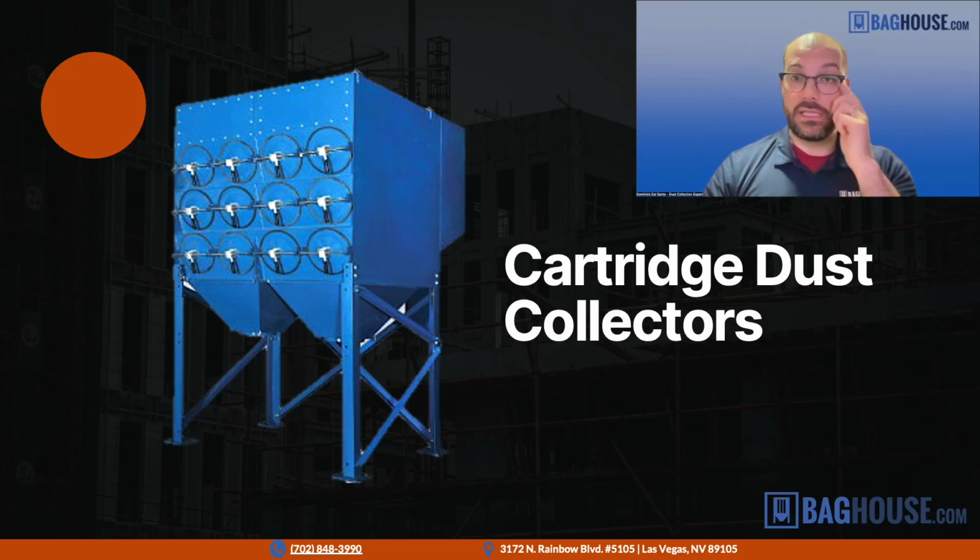So usually we see these retrofitted into existing baghouses, but sometimes we do new systems with them as well for mining and cement. More often they're used when we have bin vents or small systems as opposed to a very large baghouse. But absolutely something that you should investigate in some of your applications with someone like us to see if it's a viable option, because there's a lot of benefits to switching to the pleated filters in your baghouse.